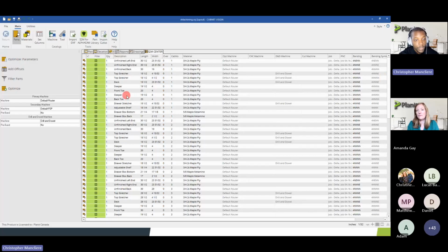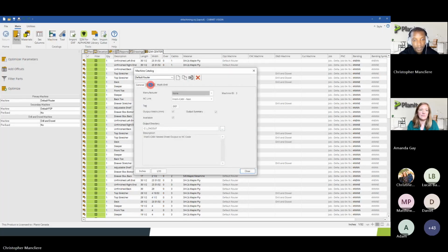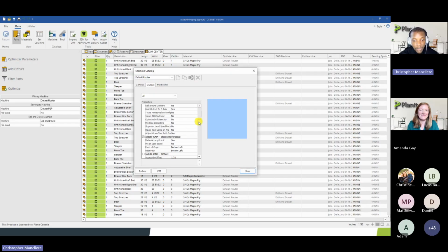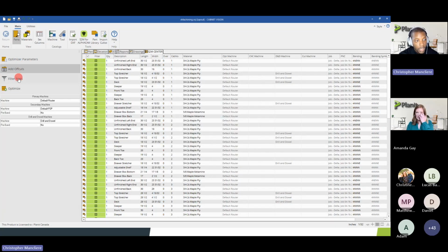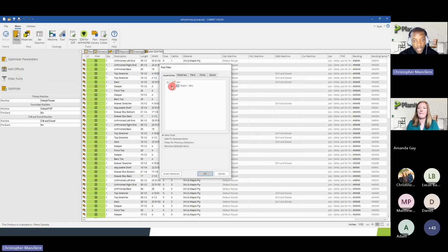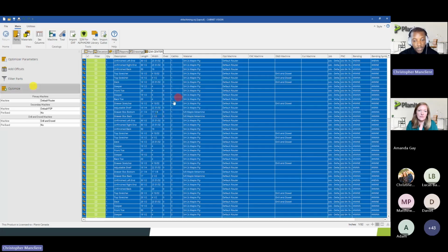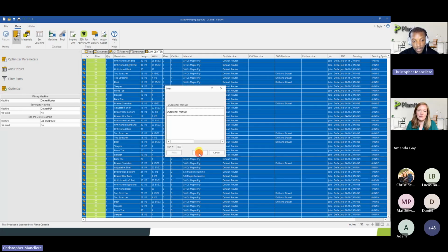Now for the boundary, so let's do a practical example. As I said, I'm using true shape nesting, and right now exterior, so I'll put, for example, 4 and 4. And I will filter or just cut cabinet parts. Just standard cabinet parts, where I have more chance to find small parts. And let's run it.